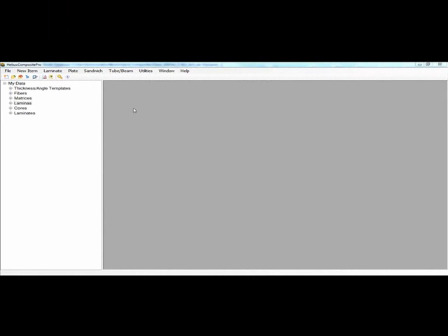This video will demonstrate how to conduct a progressive failure analysis of a composite laminate using CompositePro. A progressive failure analysis looks at each individual ply in a composite laminate, and when that individual ply fails due to a composite failure criteria, that individual ply's mechanical properties will be degraded to a fraction of the pristine stiffness.